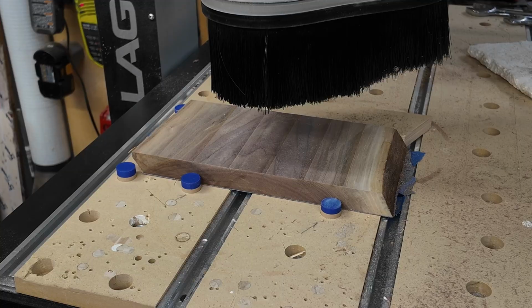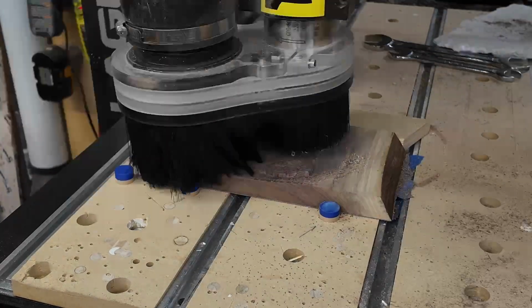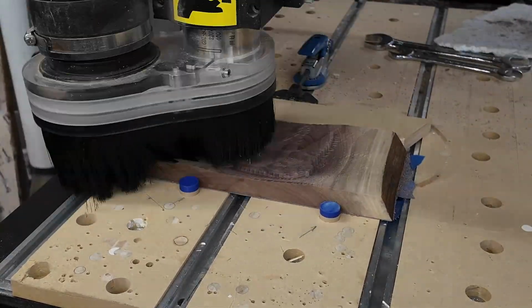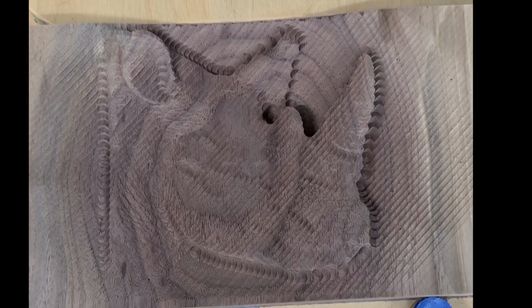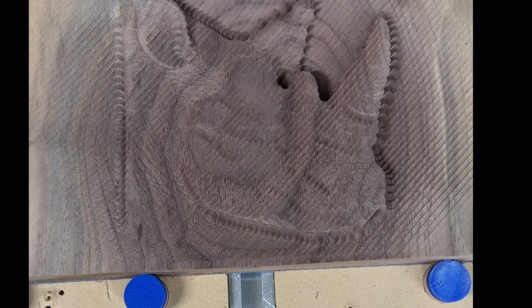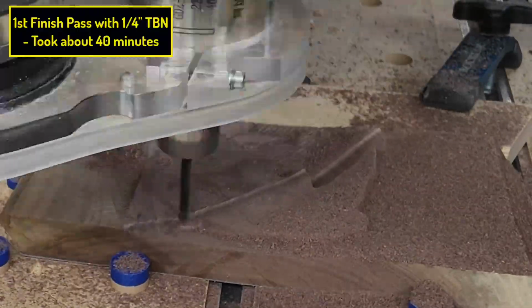All right, ready for the first roughing cut. This one's estimated to be about 55 minutes. Total carving is between 5 and 6 hours for this small Rhino head. This is what the carve looks like after the roughing pass. Starting to take shape. It'll take a lot more shape after the next pass, which will be the first finishing pass with a 1/4 inch ball nose. And the next step was the first finishing pass with a 1/4 inch ball nose. Took about 36-40 minutes.